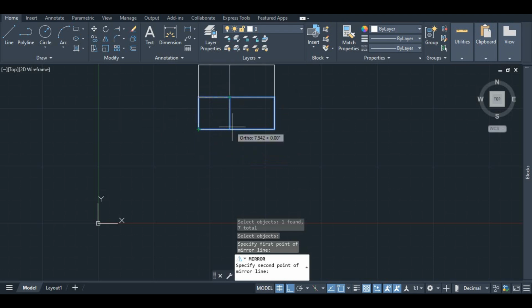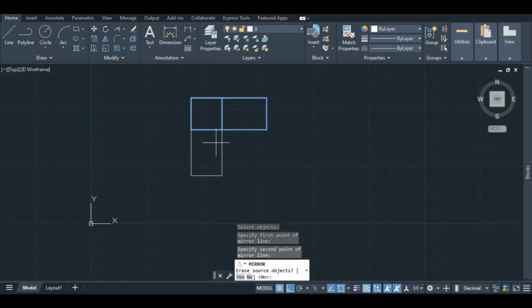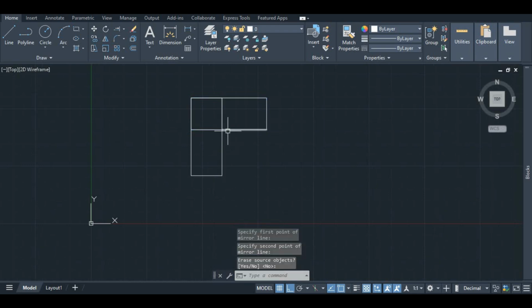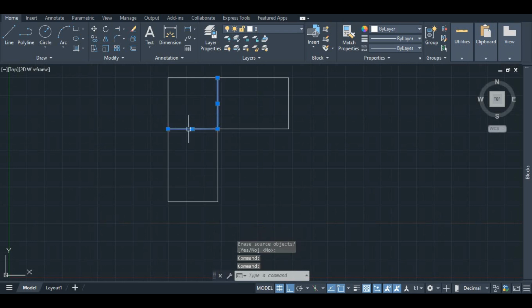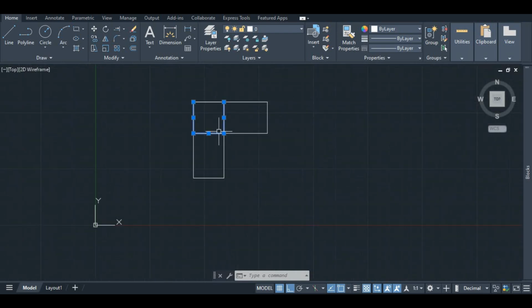But let's assume you want to mirror, you can also mirror along this axis too. Let's see how that works. Yep. So you can see that this also mirrors down like this, and then you have this drawn. So that's the advantage of mirror. And in order to enable your mirror, you need to press enter, and once you press enter, you have your mirrored object right here. This is just like rotating the object in a certain way,